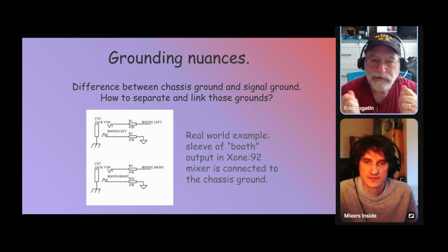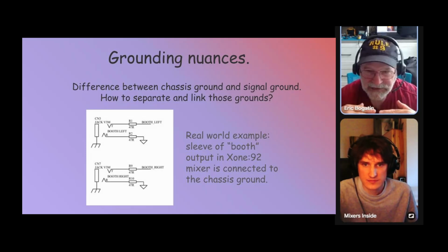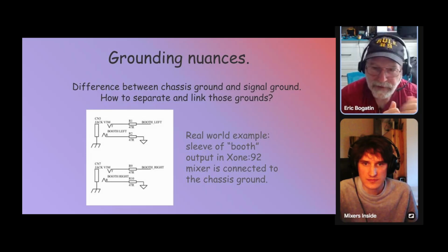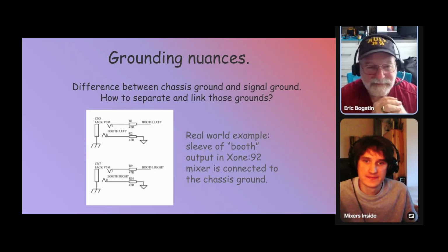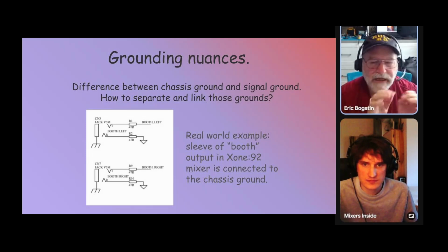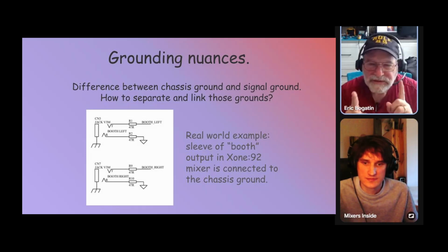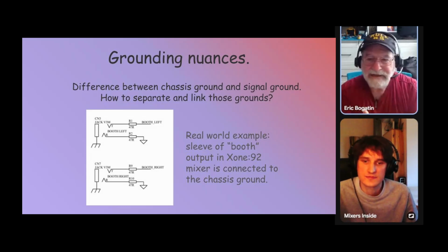And if you have current in the chassis, you should never use the chassis as an intentional return path. Yes. But sometimes you get currents in there. If there's no current flowing in the chassis, every point on that chassis has the same voltage. There's no voltage drop. The only way you get a voltage drop is current flowing in either inductive or resistive paths. If there's unintentional or intentional current flowing in the chassis, that means different points of the chassis have a different voltage. It's like any return path, you have a different voltage on those return paths.